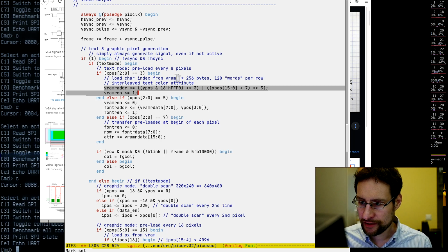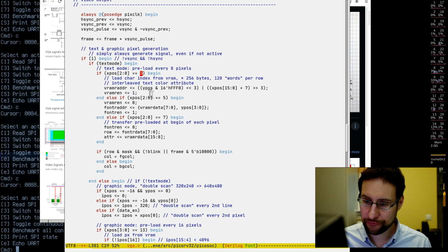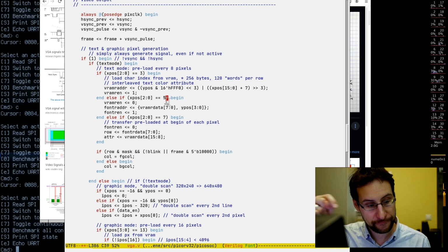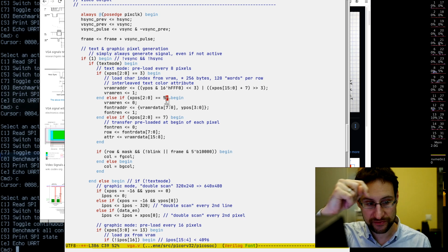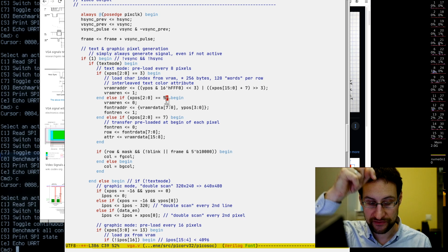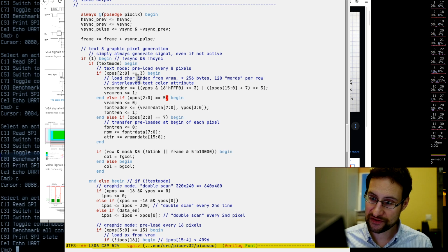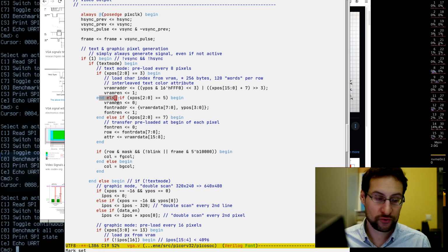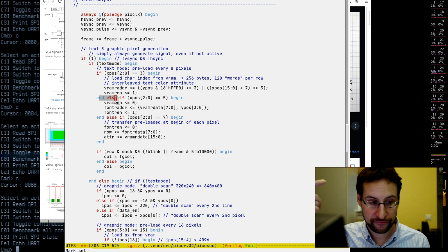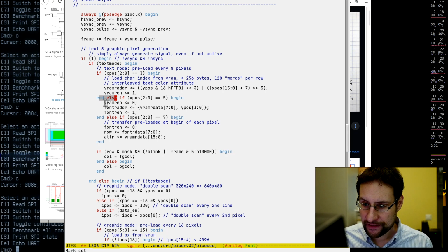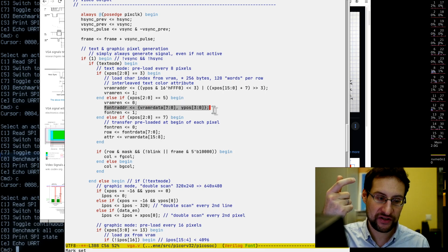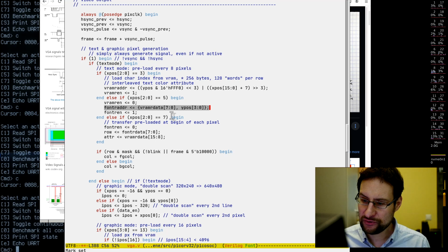Then 2 cycles later, you see a 3 and then 5. So 2 clock cycles later, at the 6th pixel, this is addressed by 0, so the 0 bit and so on. The 3 is the 4th, the 5 is the 6th. So 2 clock cycles later we have a valid output from the memory. We disable the memory enable, and this VRAM data is the output of the memory. We use this address